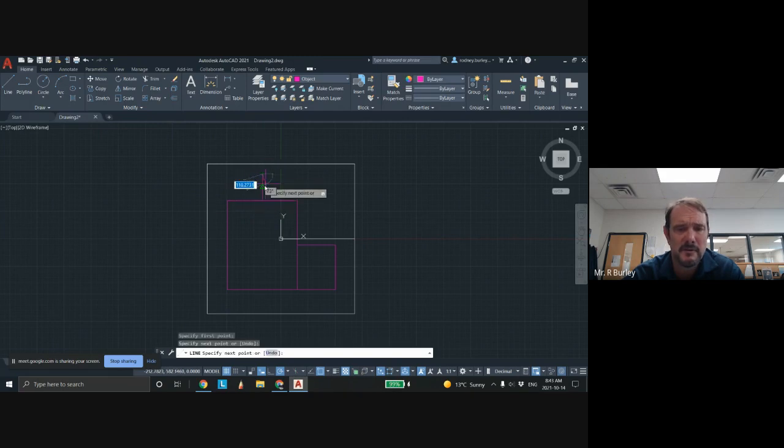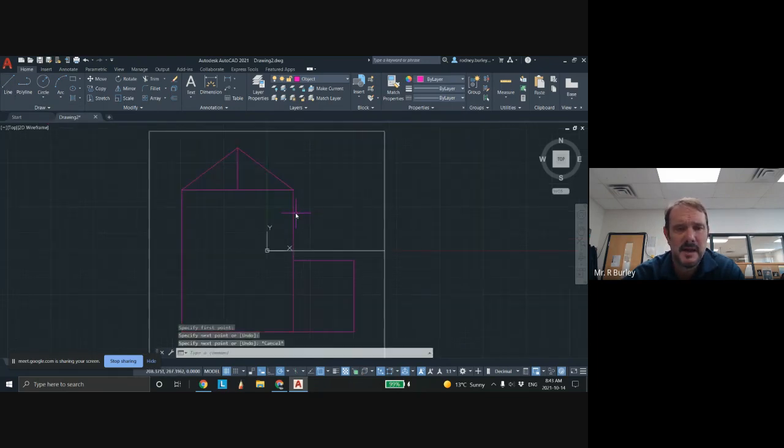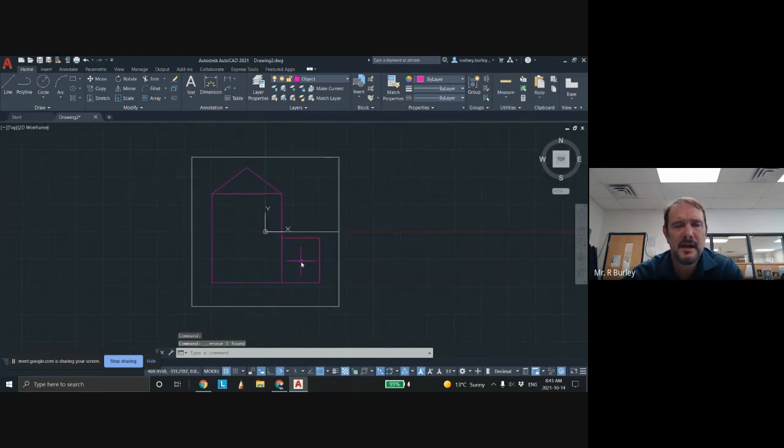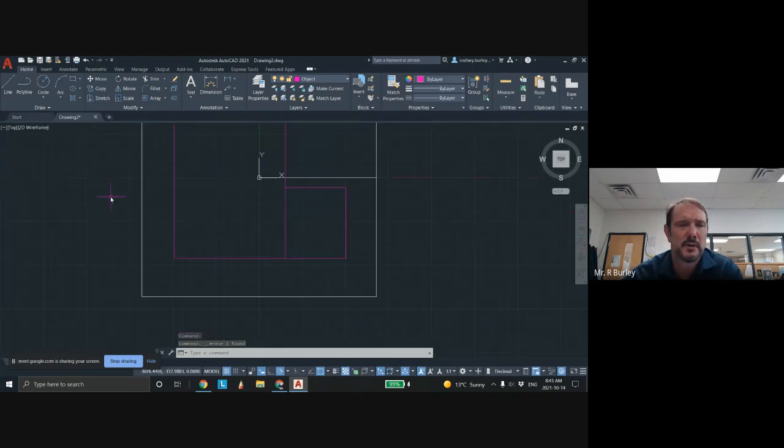I'm going to walk up for the roof, and I come back down here, some arbitrary angle, and same with here, back down. And I don't need this guy right here. Let's get rid of him. And now what we can do is let's put the garage door in. So I can offset with garage door. I can go like this. I can say, let's offset, I don't know, 20 millimeters. And I could offset this guy here over and this guy here over.